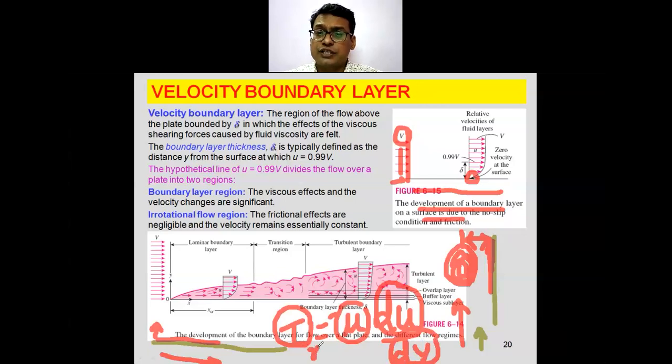We are considering these shear stresses in the x direction. So for the shear stresses in this x direction, there is a velocity gradient in the y direction. This is our y direction. Understood this point? The velocity gradient in the y direction is observed at this point. Because of the zero velocity at the surface, on the subsequent layers there is a gradient observed because of the inside shear resistances, inside fluid resistances caused by the viscosity, and the velocity gradient in the y direction.